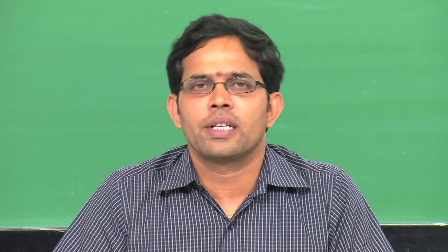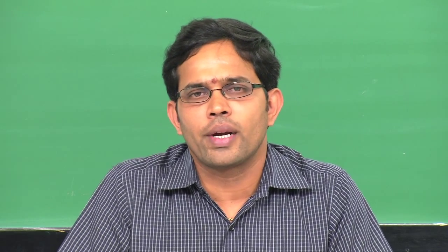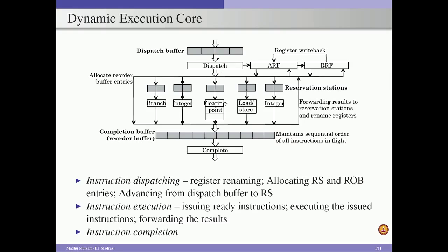And if the instruction is a store instruction, then in addition to the complete stage, we also have a retire stage, and in the retire stage, we are writing the values to the memory. So, this is the core of the Superscalar processor. The dynamic execution core is the critical component in the Superscalar processor, which executes instructions in out of order fashion and commits the instructions in order.